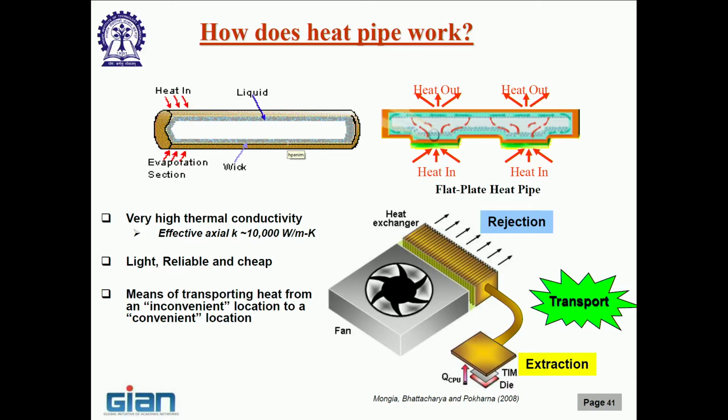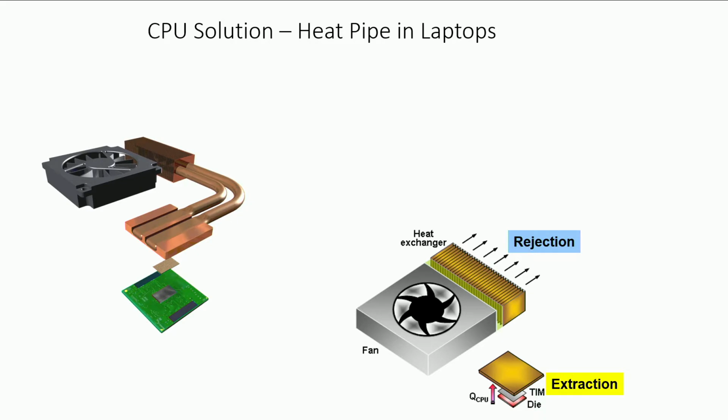How does it work is the question. So, I have an animation over here which will tell you. This is how this hardware that I passed around looks like. This was a special one where one of the heat pipes came on the fan casing, but forget that, that is not a standard one. It typically will have either 1 or 2 heat pipes getting into this finned heat sink and a fan blowing air through it.